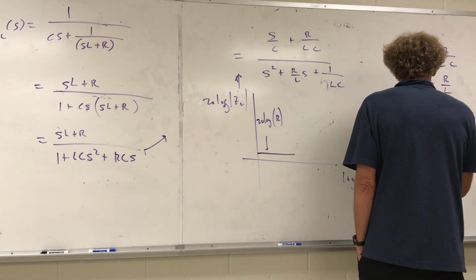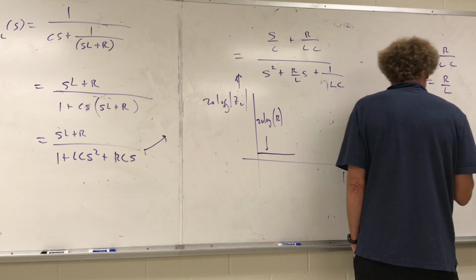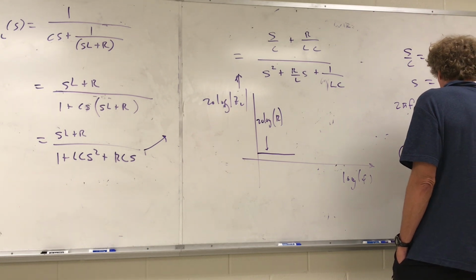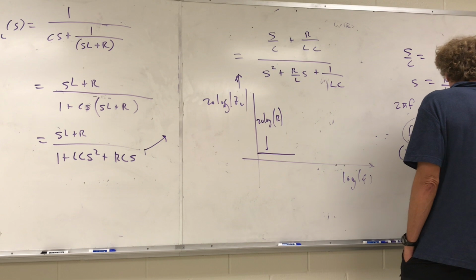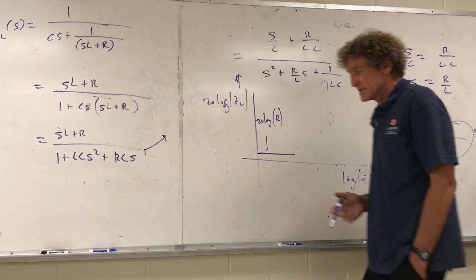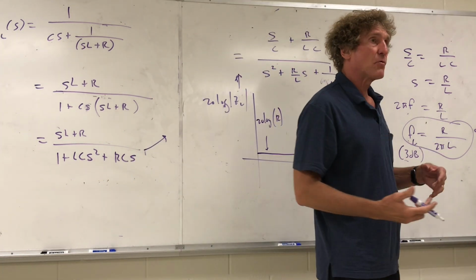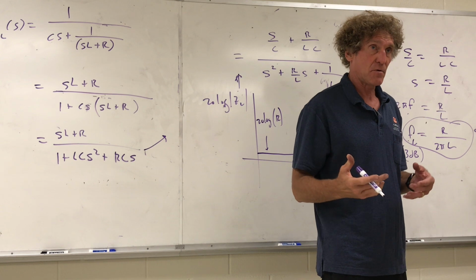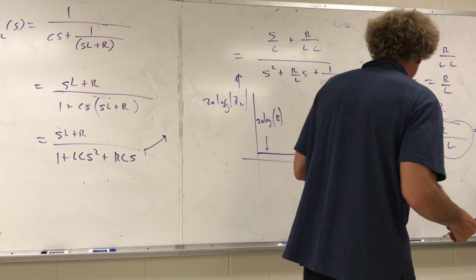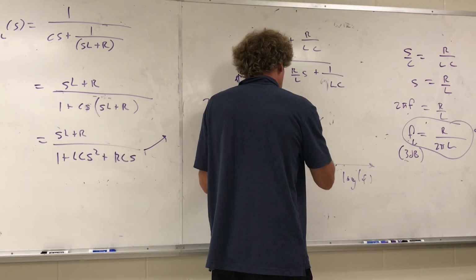And you see that the actual first cut frequency, or the lower 3 dB, he does not have this in the book, will be equal to R over 2 pi L. I want to say this is usually very low. Usually the resistance is of the order of tenths of ohms, maybe less, and L is of the order of millihenries or microhenries. Y'all follow? It's a very small value. So normally we ignore this, but it'll go here, and then it'll start going up at a rate of plus